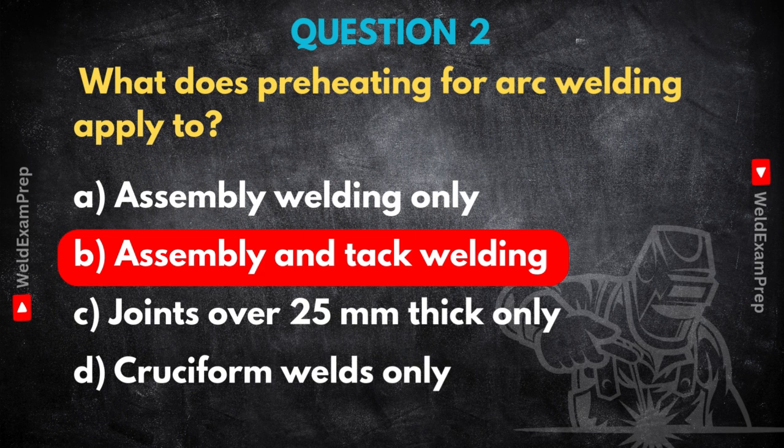Absolutely. Verify that temperature with temp sticks or pyrometers before any arc is struck, tacks included. It's about being proactive right from the beginning. That's a great point. A small detail with potentially big consequences. Okay, moving on from process controls to material behavior itself.